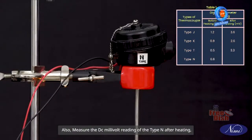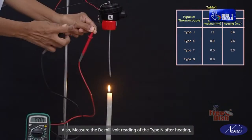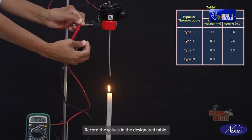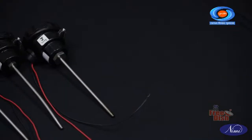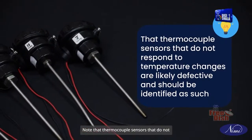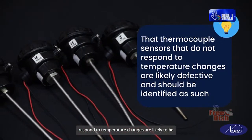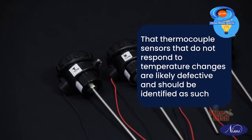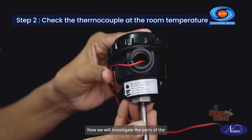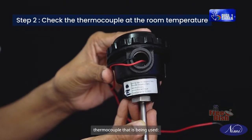Also measure the DC millivolt reading of the type N thermocouple after heating. Record the values in the designated table. Note that thermocouple sensors that do not respond to temperature changes are likely to be defective and should be identified as such. Now we will investigate the parts of the thermocouple that is being used.